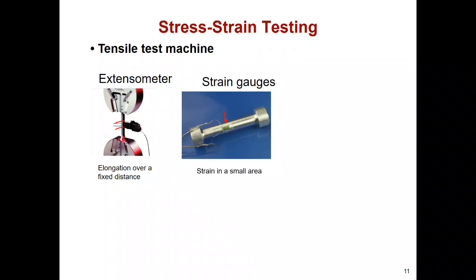The strain gauge looks like this, with an electrical wire connected. Due to deformation, the length of the wire changes. When we apply a current, due to the resistance in the metal, the voltage drop can be detected. If this length increases, the resistance R also increases, which means the voltage changes slightly. From that, we can check how much the solid material increases or decreases.